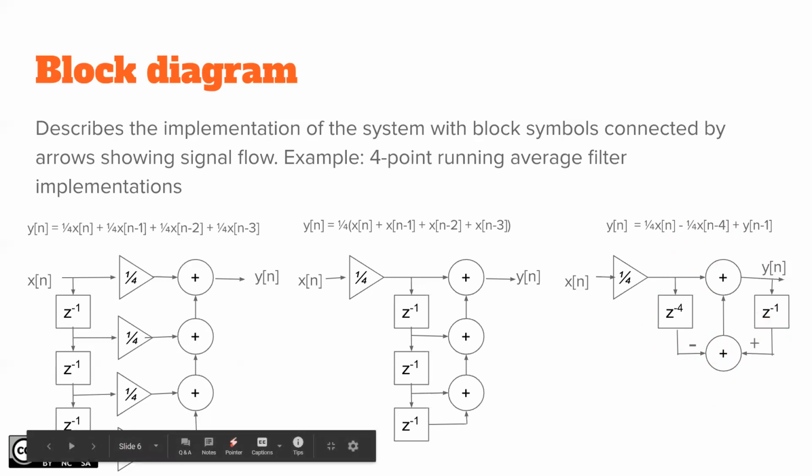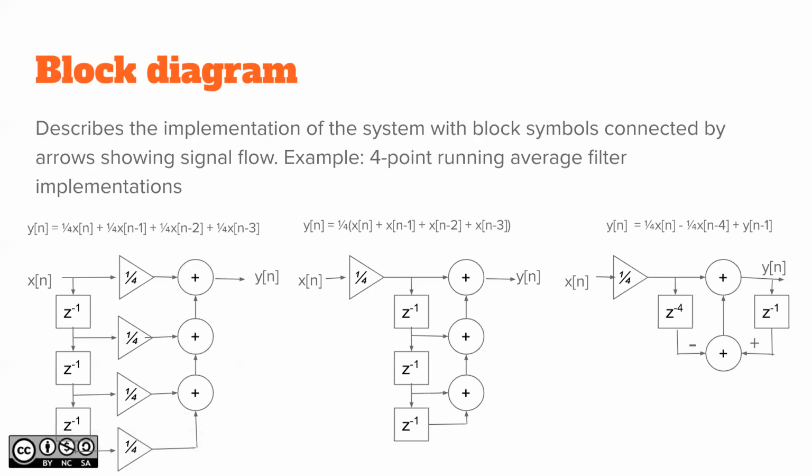Multiplication is slower than addition. Simple logic. In modern processors, they usually go equally fast, but take any, say, 8-bit processor: the multiplication is slower because if you do 8 by 8-bit multiplication, in any case, you need a 16-bit integer to save it. So that one already takes more time.